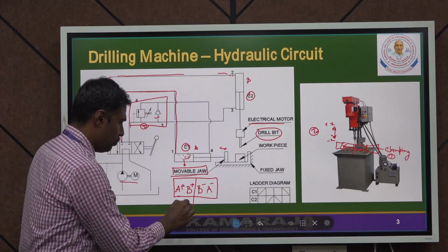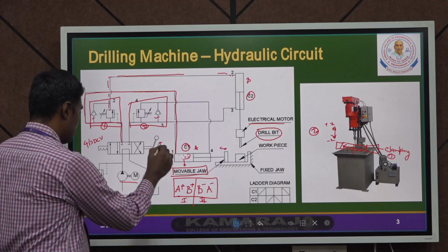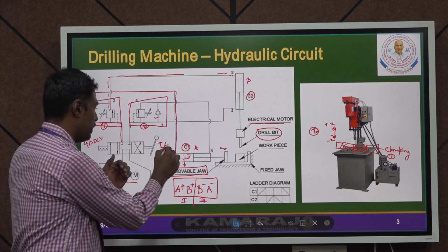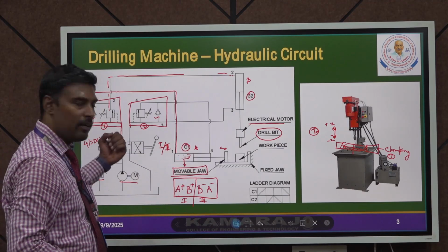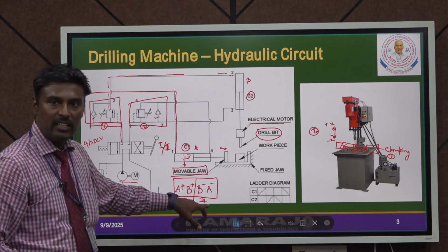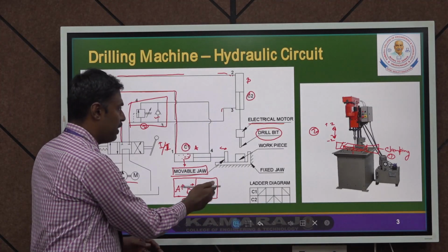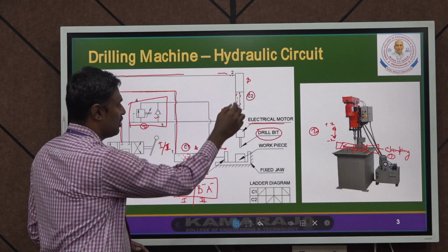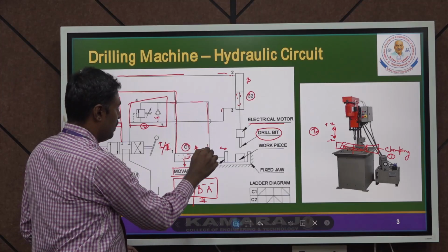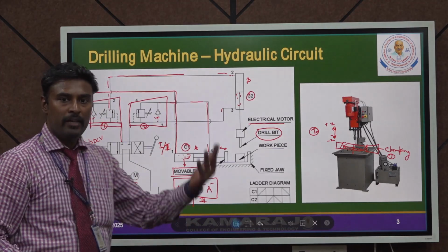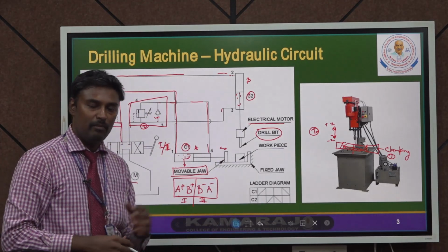This is for grouping one, and this is for the next grouping. So this is for the first grouping, and this is for the second grouping. If you actuate the lever, group 1 is extended. If you pull the lever back, then group 2 is actuated. Once group 2 is actuated, the fluid supply goes to cylinder B, therefore B minus is actuated. Once a back pressure is created, here you have the sequence valve circuits. After the sequence valve is actuated, cylinder A is returned back. This will be moved to and fro. So this is a proper sequence valve circuit connection, because we have already discussed it.